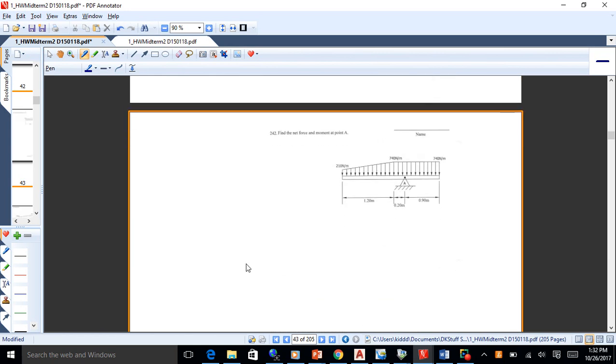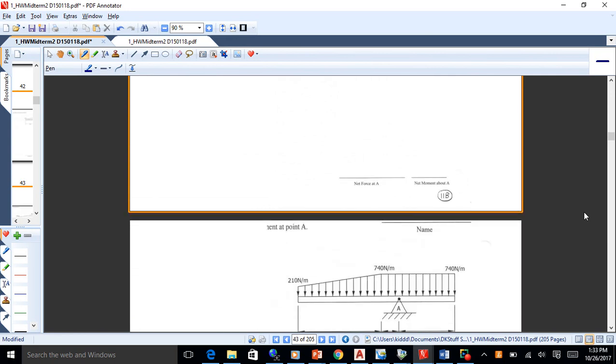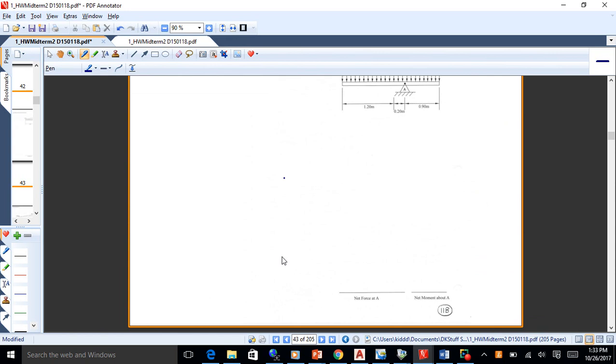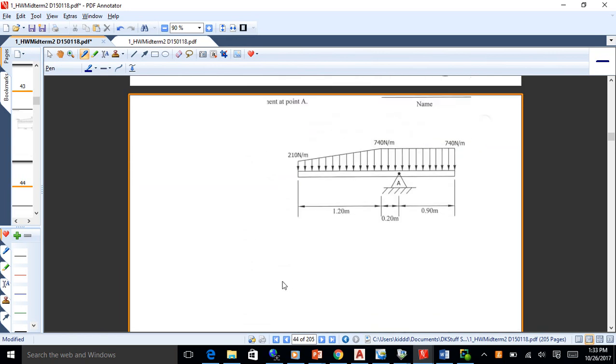All right, then we have this one here. Now we just want to find the resultant at A that occurs when you have this loading diagram. I would do this one piece by piece and work my way on down through it. To accomplish that, I would break it up into pieces. What you've got there are 2 rectangles and a triangle. You're going to want to find the centroids of these, and then find the distance from point A to those centroids.